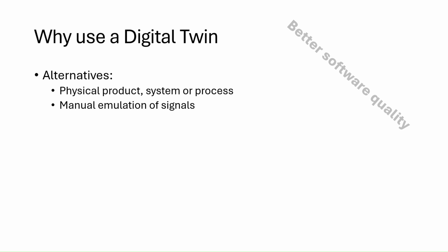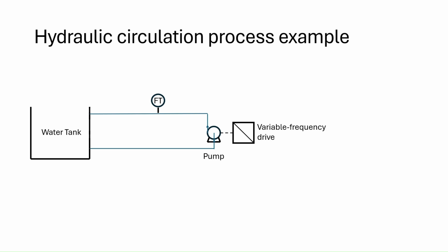And just if we look at the example we had earlier, here the simulation of this system would be simulating the input. So the flow, for example, you would simulate that, and then you would look at the PLC program if it gives you some pump signal, so the 0 to 100% signal for the VFD, that makes any sense. But as I've already told before, this is a static change.